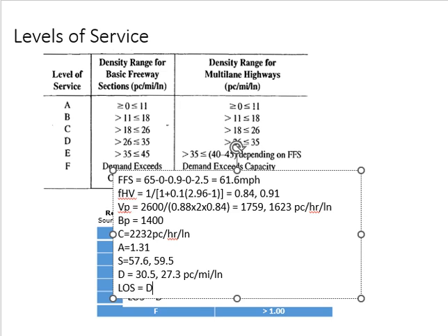One mistake which people usually make in projects is they do it the other way around. They try to merge the two directions and calculate the level of service. That is wrong. Level of service is always for each direction. There is no such thing as the highway level of service. We do it at the intersection, but not for the highway.